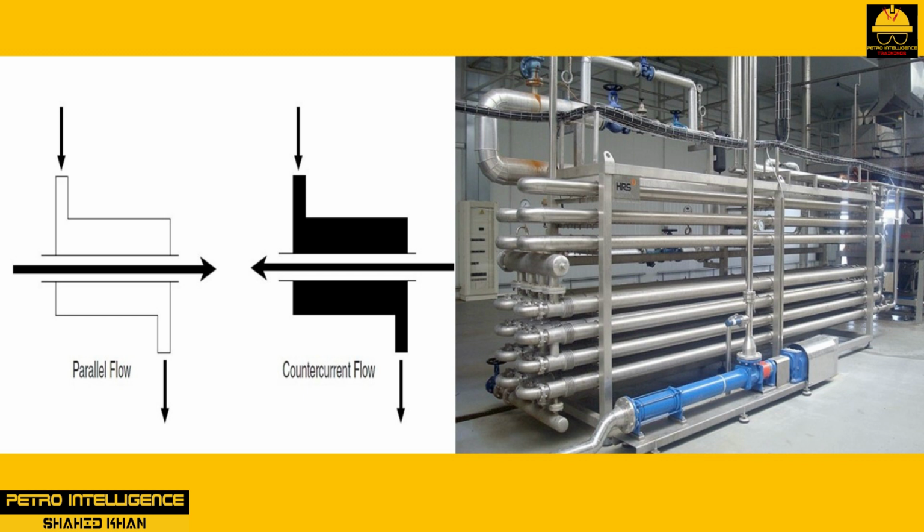One of the system limitations of double pipe heat exchangers is the flow rate they can handle. Typically, flow rates are very low in a double pipe heat exchanger, and low flow rates are conducive to laminar flow.